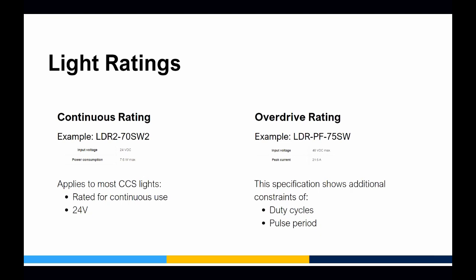If you're using a Gardasoft controller or a CCS overdriving controller, it's not as critical to know this information because those controllers have built-in safety. But especially if you're not using one of those controllers, it's important that you understand what the overdrive rating is for each light so you don't give it too much power and burn it out.